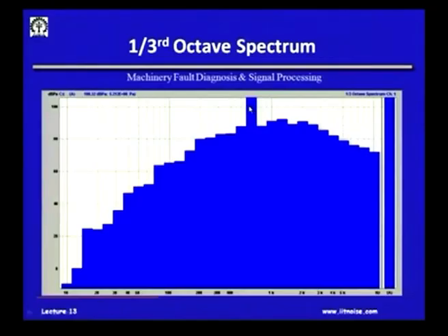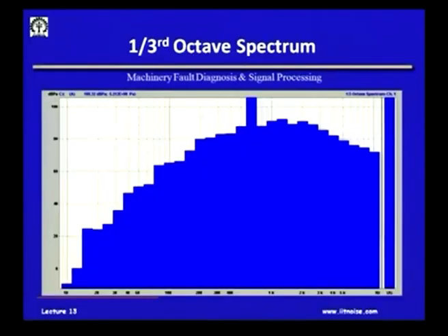And if there are 5 such motors in that plant and there is a small variation in their speed, this is giving rise to beating. Obviously, I cannot bring down the beating phenomenon, because for operational reasons some of the fans rotate at slightly lesser speed than the others. So, all I can do is to reduce the effect of the large noise which is heard because of the beating, is to put an enclosure on the motor.